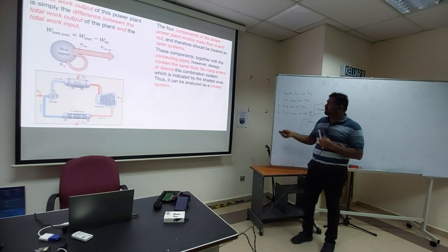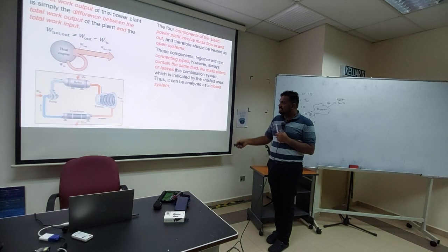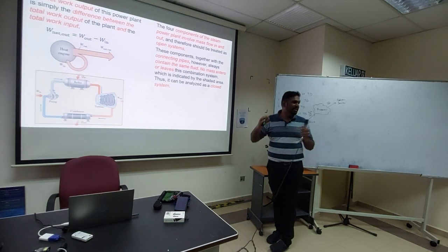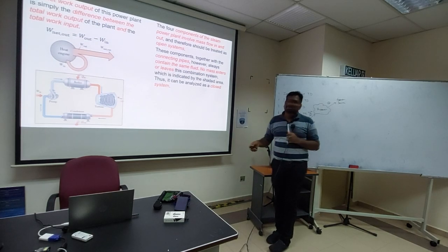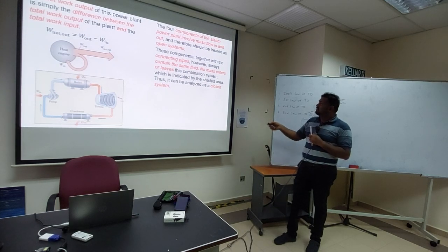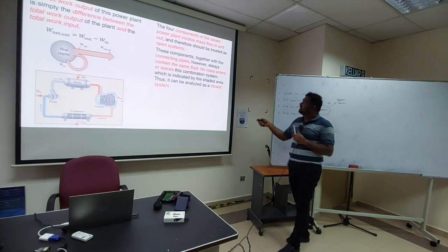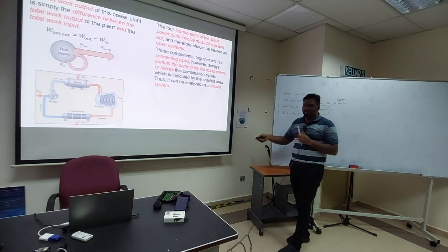So internally it can be considered an open system, because mass from system 1 is entering system 2, and it can also be considered a closed system, because all these things are inside a bigger system. All this is just components of the larger closed system. These components together with the connecting pipes always contain the same fluid.